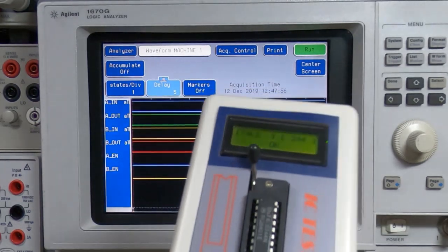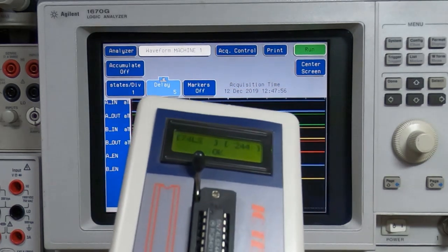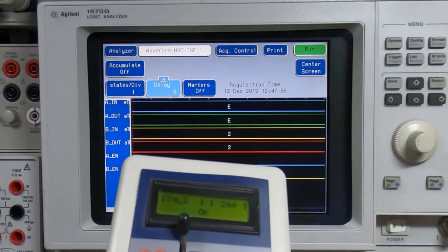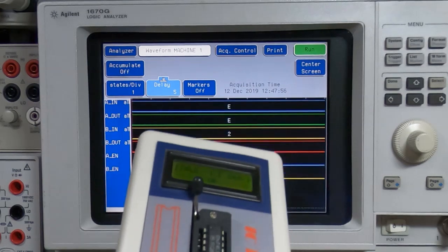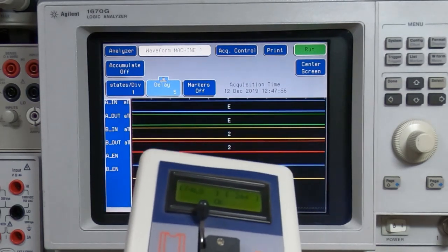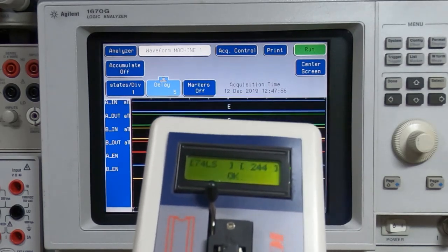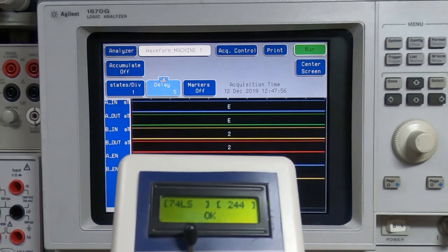It's also the reason I don't cut the pins off devices when I remove them. I want to be able to see exactly what was going on in the board, and it resolves any question marks I may otherwise have as to why the board wasn't working when the signals kind of looked okay. So with marginal cases, it's not necessarily the problem with the device you take out. It might be the devices it's feeding into, and so that's why I need to know if the chip itself is at fault.